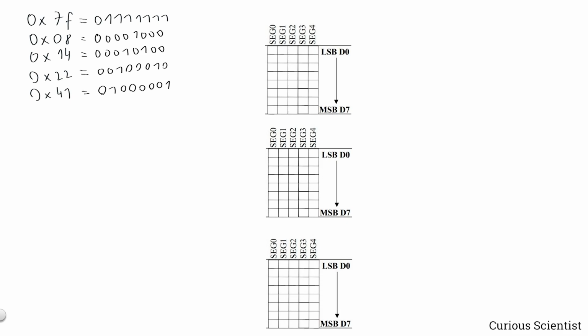So how this works is that we start from here, and then we read the numbers this direction, and then we go from LSB to MSB and see the value of each individual pixel. So that means that, for example, when we look at the first byte, then every pixel is set to 1 except the last one. So that will look something like this.